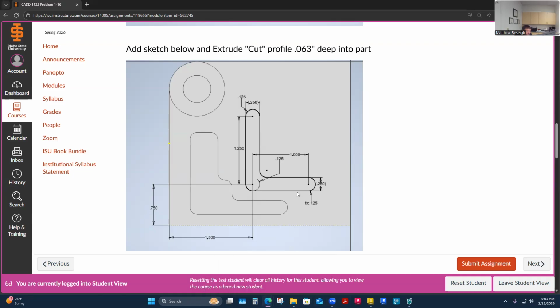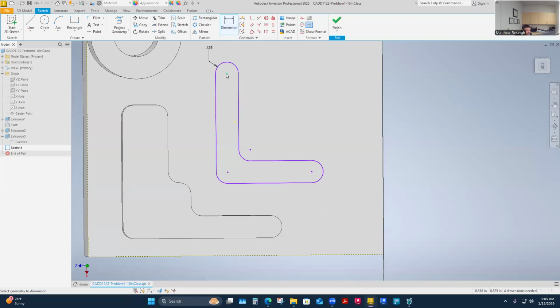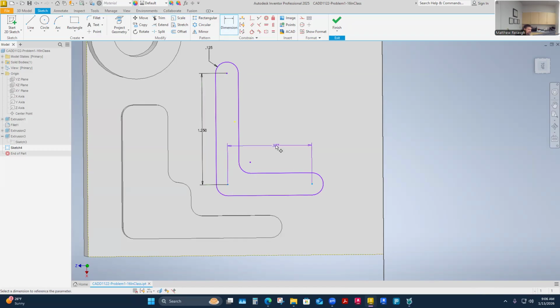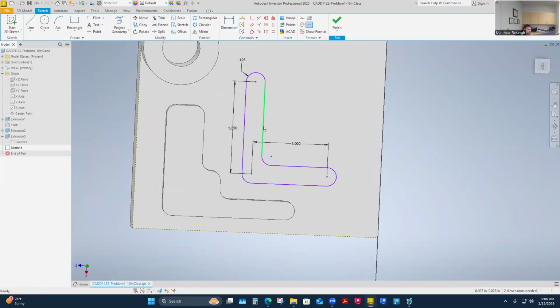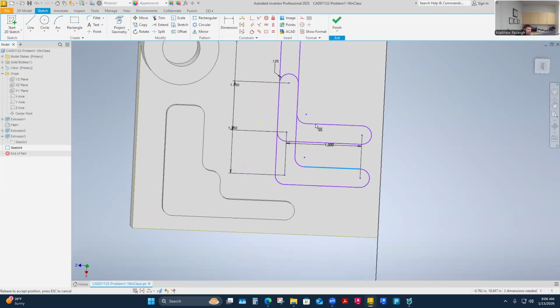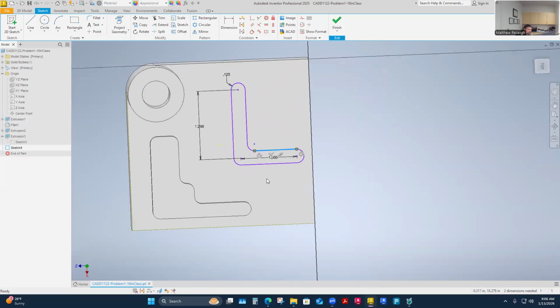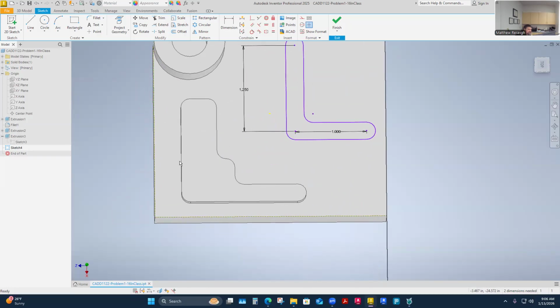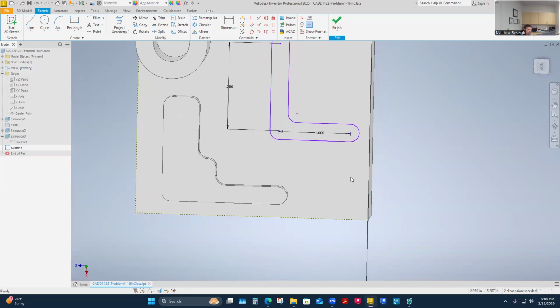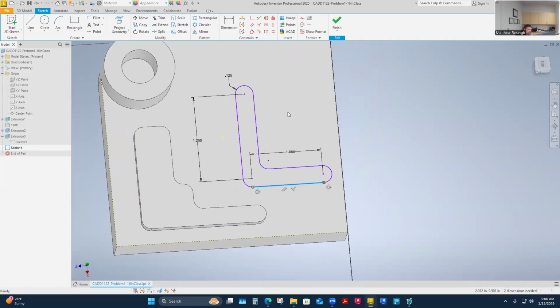At least geometric here. So 1.25 inches, an inch. Well, I can do it after this sketch. 1.25 inches, sorry. Because the last sketch on this is probably the nastiest one, actually. I think maybe. Maybe I'm wrong. This is 1 inch though here. So technically, this is a pretty well constrained geometric shape, but it's not constrained in space whatsoever. That's why it's not black at all, right? I need the dimensions to lock it in relation to something, even though it's kind of locked into itself.